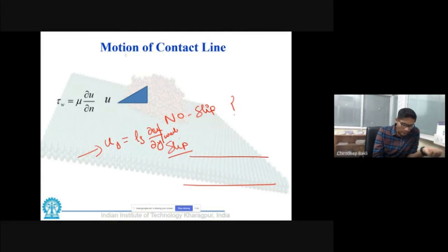By your basic knowledge, you know that the meniscus of a capillary would look like this, convex upward. So fluid is moving this side, and it looks like this, so gradually it is filling. Now the force that would be aiding the motion of fluid in the channel would be the capillary force, or the surface tension force.